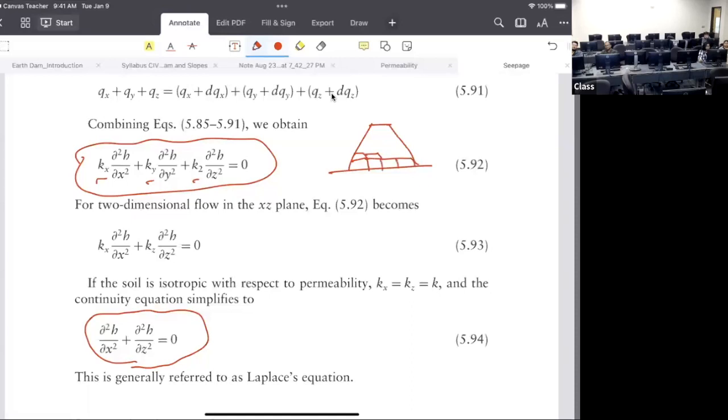Is that it? Or, more generally, we do it layer by layer, right? Any embankment. We dump some soil, have the roller pass on top of it, and then build it, dumping more and more, compacting. That's how we build it.